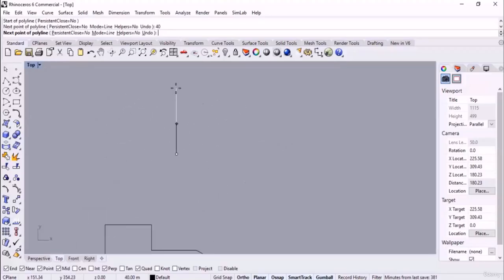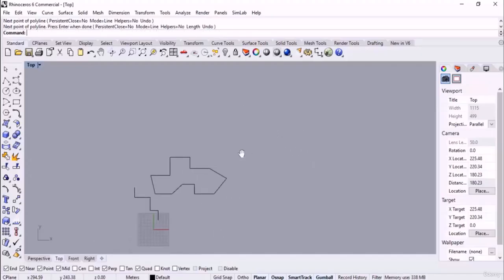Or even you can at first specify the length, for example 4D, and then we can specify the direction, but the ortho is inactive. But I can hold down shift to activate the ortho. But this is not commonly used, but if you wanted to hold down shift at first, you should specify the length and then you should specify the direction of your line.